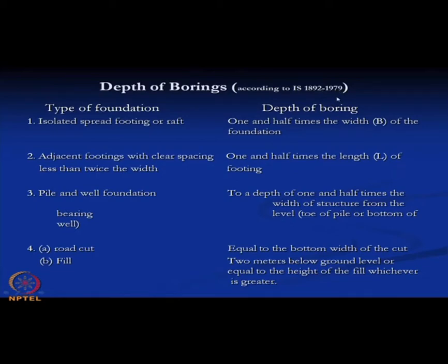So, according to that, if the type of foundation is an isolated spread footing or raft, the depth of boring will be 1.5 times the width of the foundation. This is the minimum required depth of boring for the isolated spread footing or raft foundation. This is 1.5 times the width of the foundation.